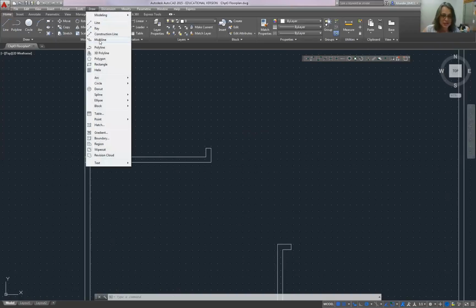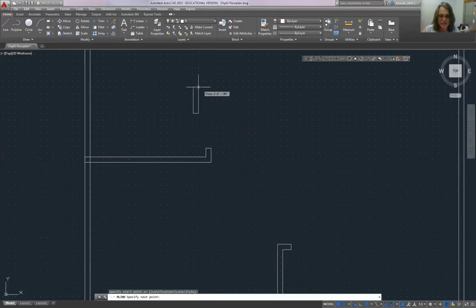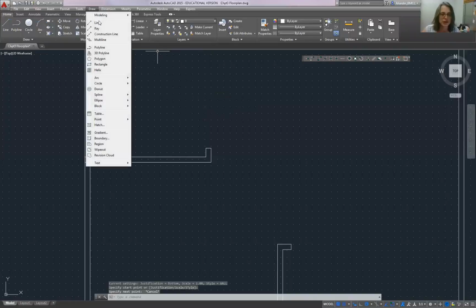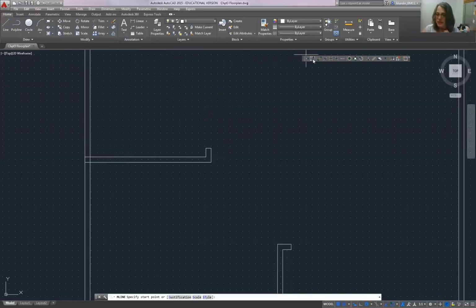I want to draw a multi-line. I just want to check something out here. If I draw up, okay. So what I'm checking out is if I draw up, I'm drawing from the outer lower corner. So we're going to draw multi-line, snap a distance from a chosen point, which is this one. And we're going to snap 0 in the X, over 0, up 2 foot 8 inches. And that puts my start point where I want it to be.